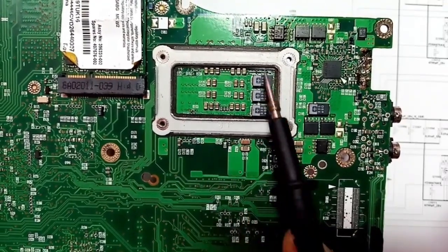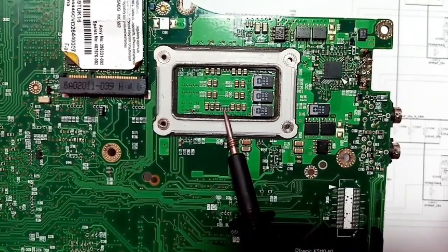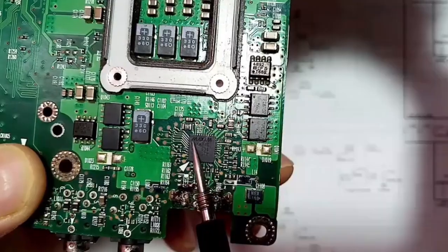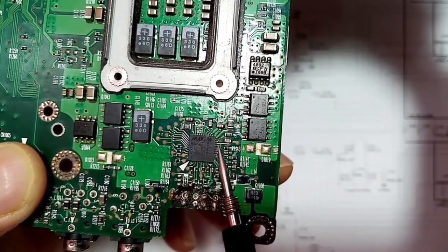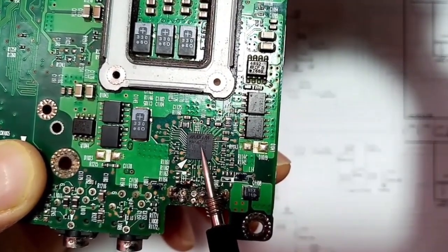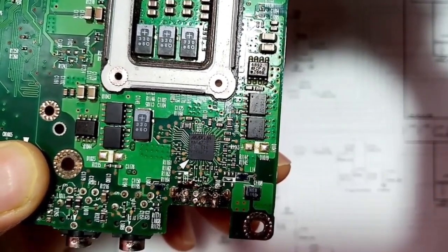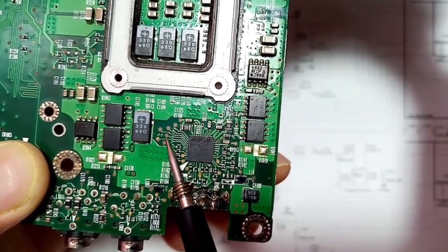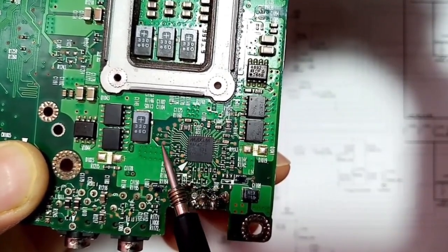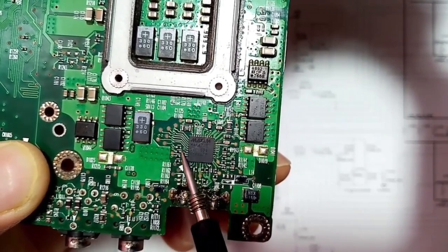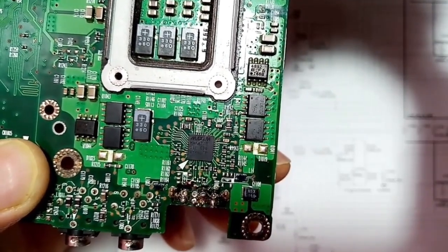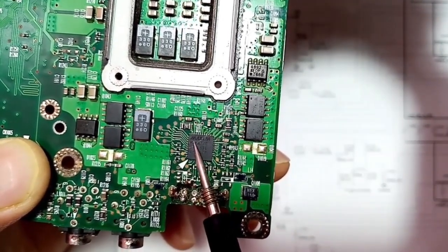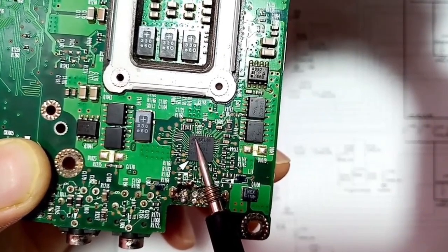As you can see, this is basically the CPU. Here we have the back of the CPU, and this is the control IC for the CPU. If you focus here, we have Maxim 8770, the same reference as we have seen in the schematic. And over here we have the test points. As you can see, we have 1, 2, 3, 4, 5, 6, and 7. All these lines are for IDs. Based on these IDs, this IC can know the exact voltage for the CPU.